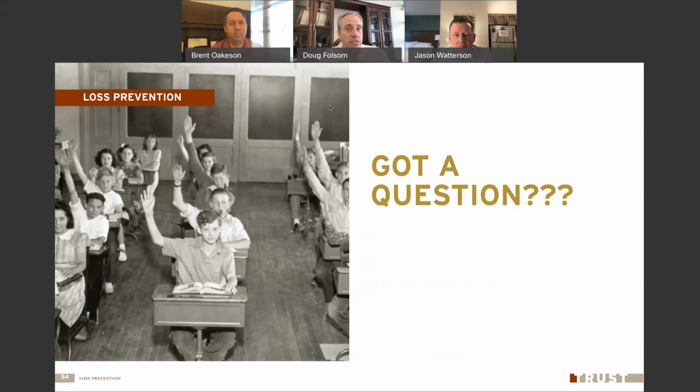People don't fall out of a scissor lift if they're not climbing up the rail in some way. I'm sure that 90% or more of those falls from scissor lifts are people who are climbing up the rails or leaning out over the rails. So just remember to stay inside the basket. Yeah, great point. Thanks, Doug.